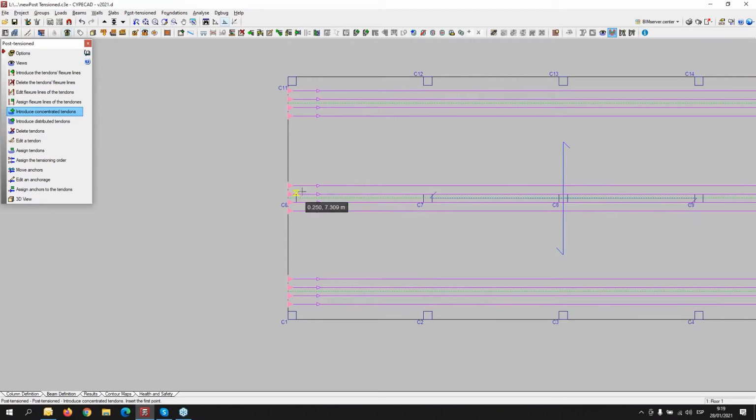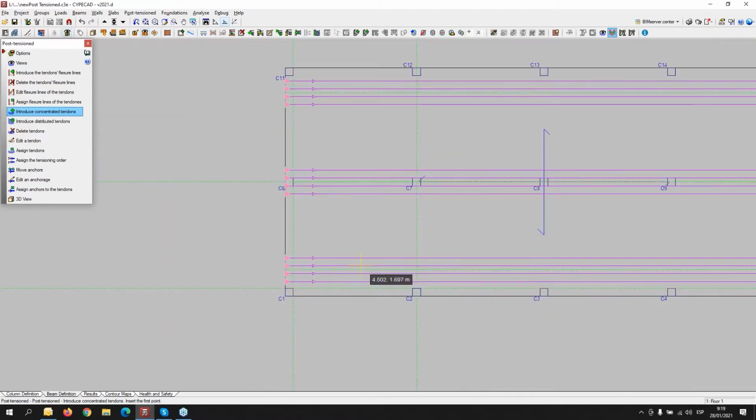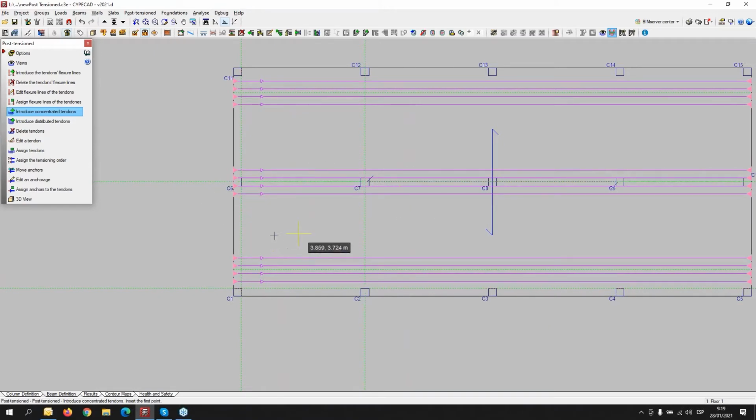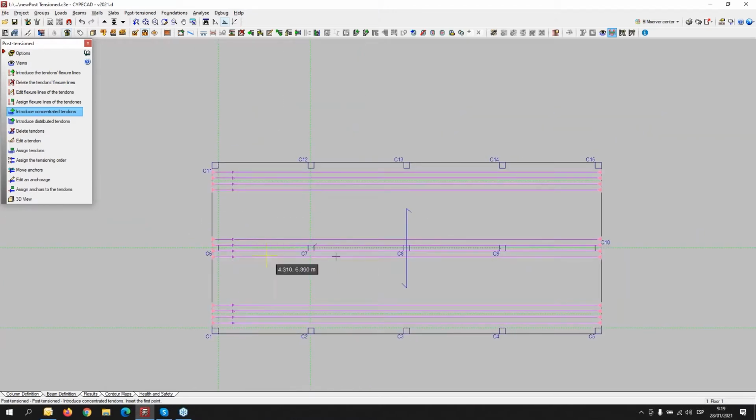So when a flexural line appears and a tendon crosses this flexural line, the natural position of the tendon will be at the bottom of the slab. Okay, so that will be very, very important in order to obtain the position of the tendons and the application of the forces of the post-tensioned cable.